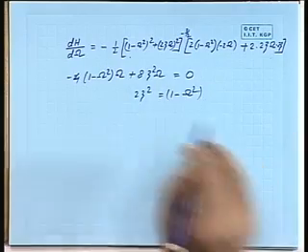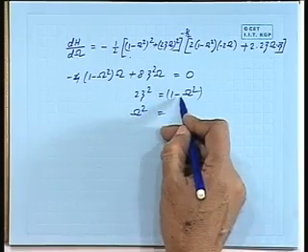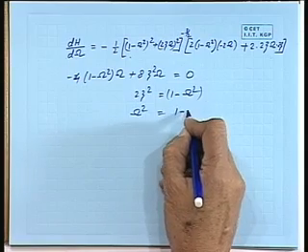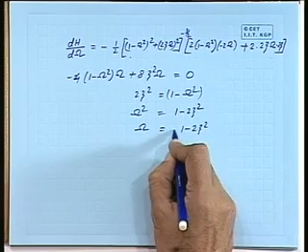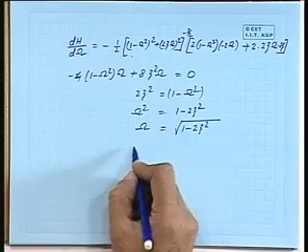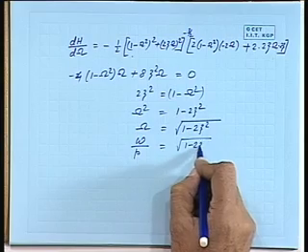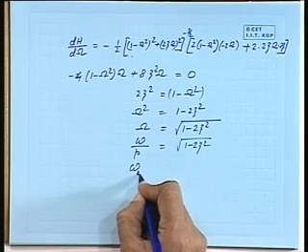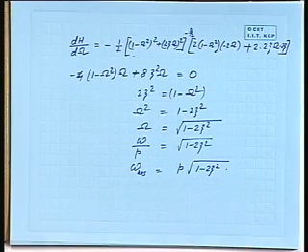So, this is the value I am getting here, and therefore, the frequency ratio omega square, if I shift here and this goes there, is 1 minus 2 zeta square, or omega is equal to square root of 1 minus 2 zeta square. Now, omega is equal to this by this, which is equal to 1 minus 2 zeta square, and therefore, omega resonance is nothing but P times this, so this becomes the resonance frequency.